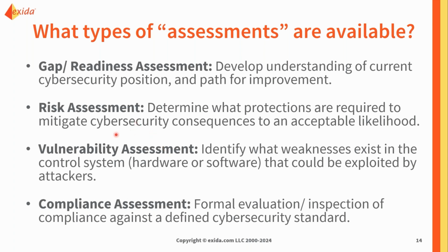For a risk assessment, this is what's done to evaluate part 3-2 of the standard and really understanding where the big cybersecurity risks are for a site, what are the critical components, and then what sort of protections or countermeasures are required to secure those critical components. A vulnerability assessment or analysis is looking specifically for what weaknesses exist in the control system. Could be hardware, could be software, could be procedural, that would make it more vulnerable to attackers. And a lot of times this is done as a supporting activity with either a risk or a gap assessment, depending on where the site is in operations.